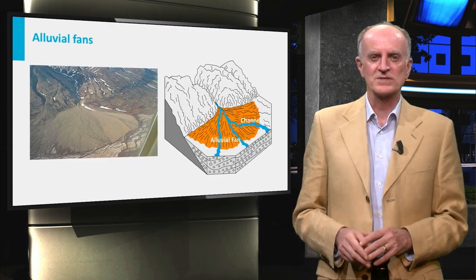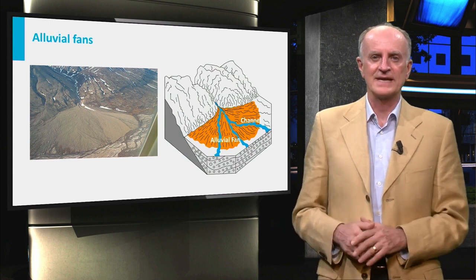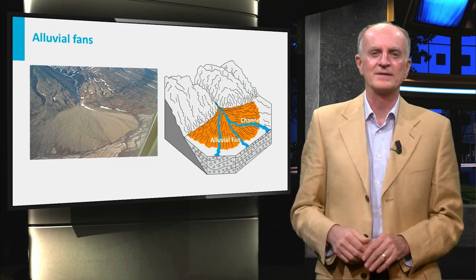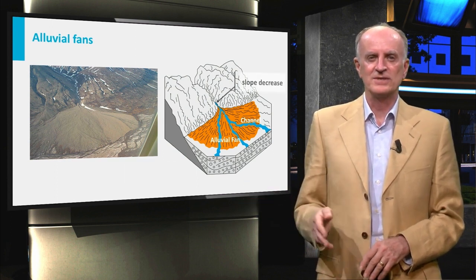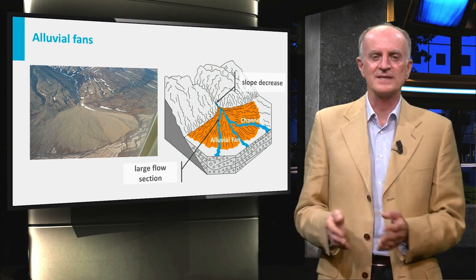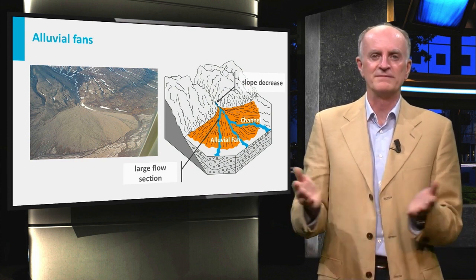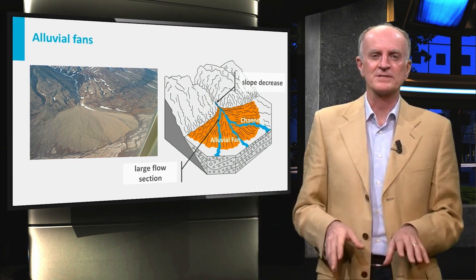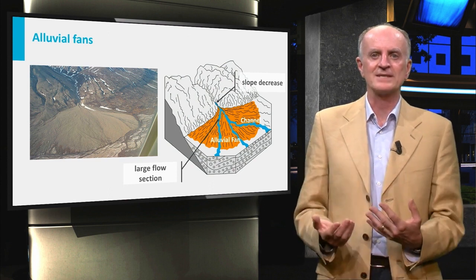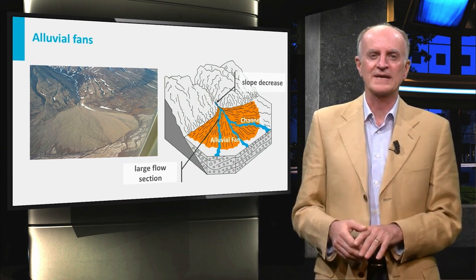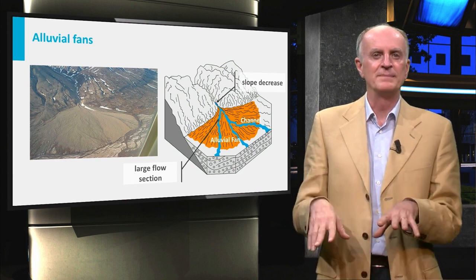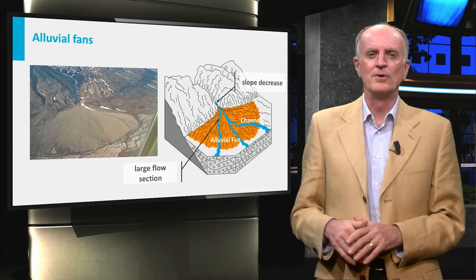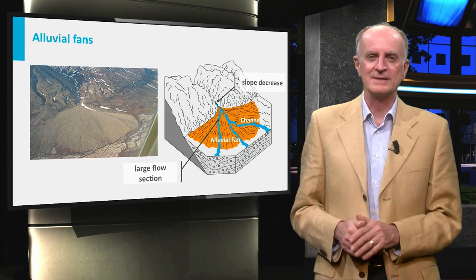A major change occurs when the river exits the steep part of the mountains and enters large valleys within the chain, or even the plains bordering the mountain themselves. At this transition, the slope of the river decreases substantially, and the section within which the river can flow becomes very large. As a result, the rivers charged with water and sediments during periods of high precipitation experience a dramatic drop in velocity and correspondingly of carrying capacity, suddenly dumping most of the sediments they have. When floods pass, waters flow along non-perennial channels, locally cleaning the sediments.